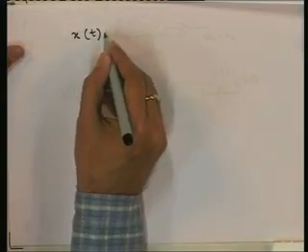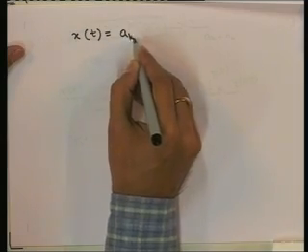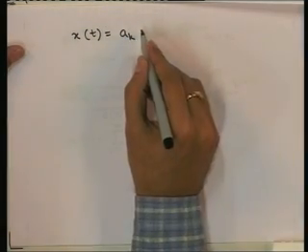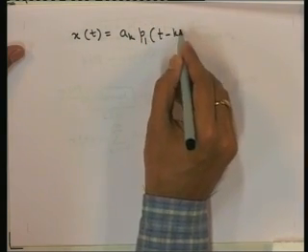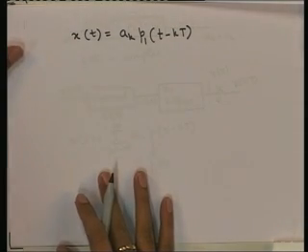To analyze what will happen, we will not assume that we are transmitting symbol after symbol. We will assume what happens to one symbol. Will we be able to demodulate if we transmit just one symbol? If we can demodulate one symbol, we can demodulate the next symbol also. So suppose that we transmit just one symbol, so that x(t) is just the kth symbol. It is transmitted between kT and (k+1)T, so a_k p1(t minus kT). This is what we have transmitted.